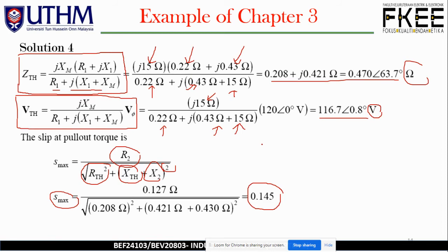let me go back to the phase value over here. I forgot one thing to tell you, so don't get confused. This is nothing but the V phase. So what should you do with the V phase? We have over here the V line divided by square root 3.